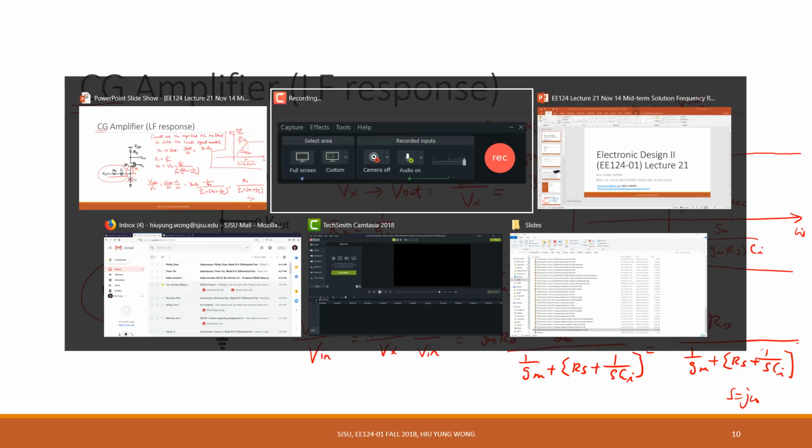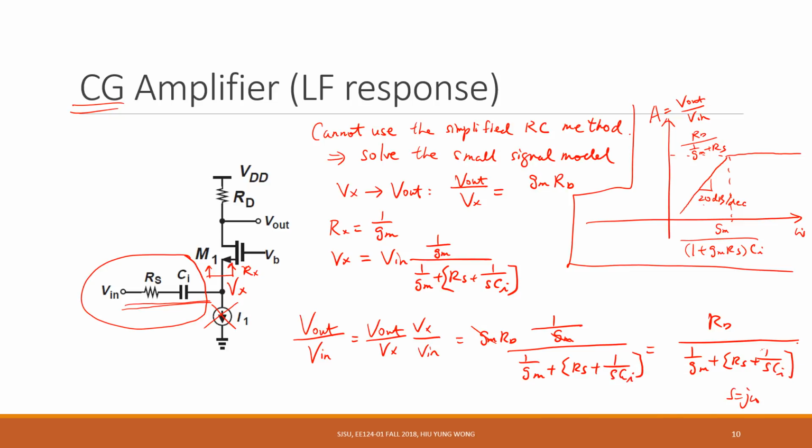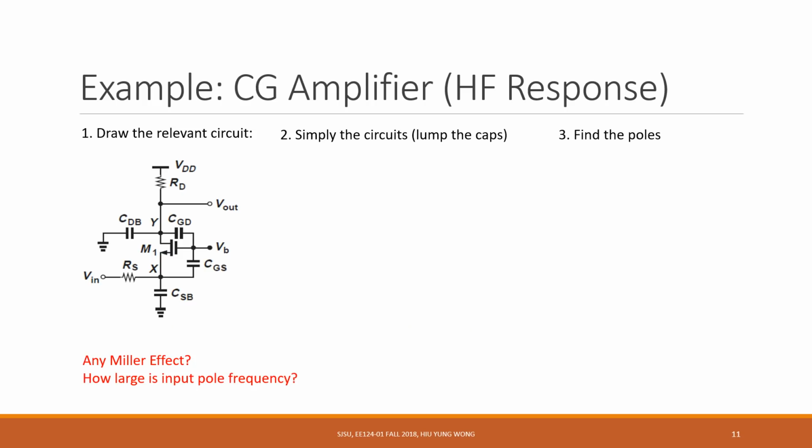We have this circuit, and at high frequency we're going to short the C1, right, because it's a large capacitor. So we have this one. Remember, V in goes to Rs, and then you have a current source, which will be open. Then you have this transistor and resistor. Gate is biased, so this is the common gate amplifier.